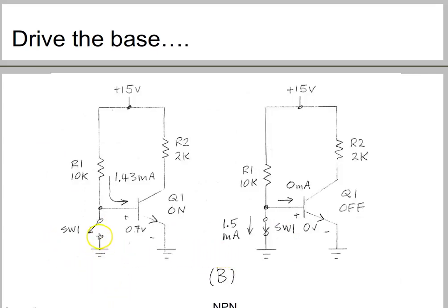And the second method uses a parallel switch with the transistor base emitter leads, and when the switch is closed, the voltage between the base and the emitter is held at 0 volts, which prevents the current flowing from the base to the emitter, and thus turns off the transistor. And when the switch is open, in this case the base current flows, turning on the transistor.